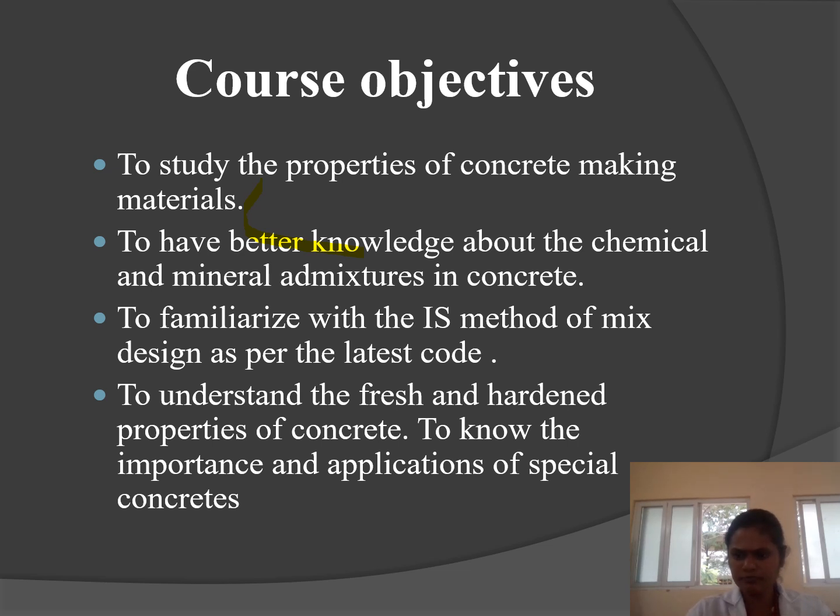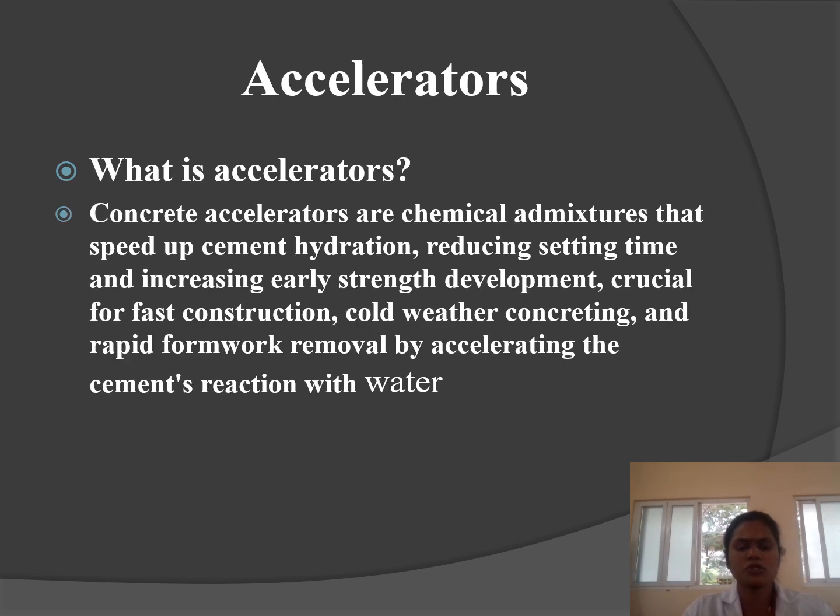Next one. What is meant by accelerators? Concrete accelerators are chemical admixtures that speed up cement hydration, reducing the setting time and increasing early strength development. They are crucial for faster construction, and are also useful in cold weather concreting.